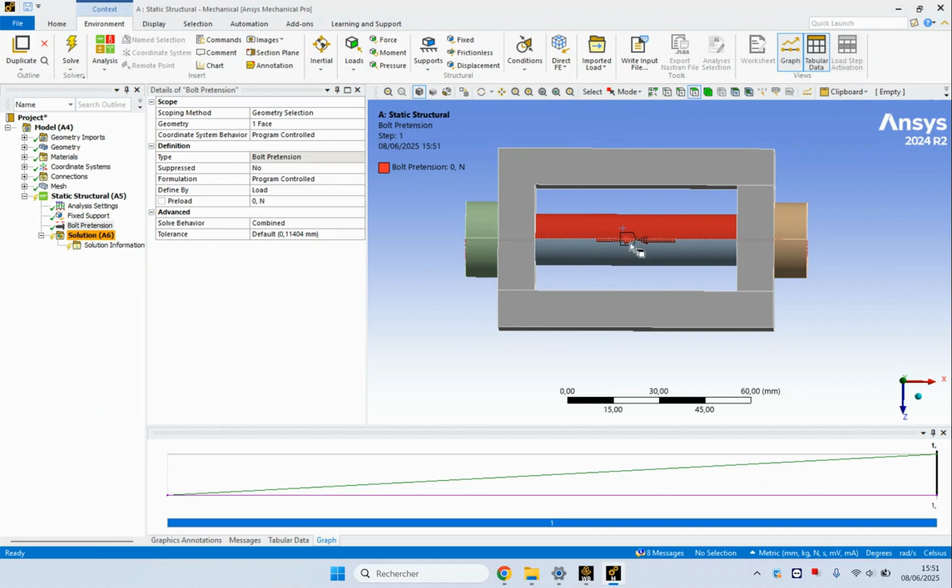But we can maybe do it later or in another video if you really want to know how to do it. So you come up here, because we didn't finish yet. You are going to add a load. If you know the millimeter, you can just come up here, adjustment, and put the millimeter. Let's say 0.2, for example, millimeter. We can change it later, but let's see. This is the bolt pretension, and we see the deformation. Is it going to be higher than this or lower than this? We don't know yet. We need to run it and see.